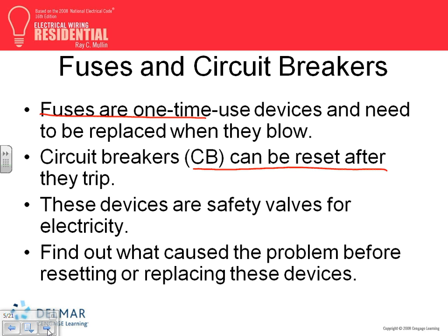It's not rated for 20,000, only 10. Or there are what they call current limiting fuses, guys. It's like a filter. You put a current limiting fuse right in here, it takes the 20,000 amps and filters it, blocks it, and reduces it down to, of course you have to size it properly, 10.